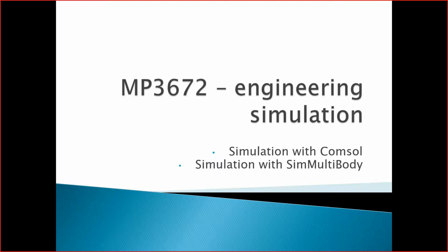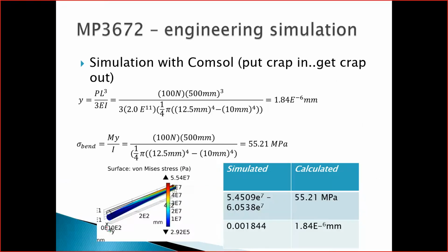So with COMSOL, simulating with FEA, we'll be going through that real question of when you run it, how do you know it's right? Where is the verification in it? Not validation, because validation is physically testing against the already calculated and simulated output, closing that loop, if you will. In this, we'll calculate it out and then run a simulation to make sure we've got some verification over the top of it. Is it in the right direction? Can we actually show that it's doing the right thing?